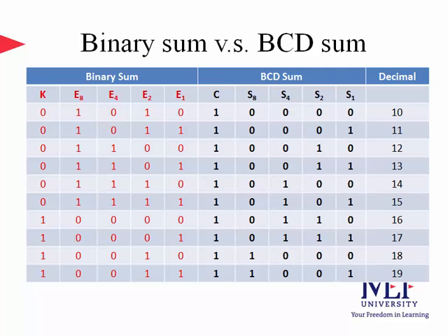As we have seen in one of our homework questions, adding the decimal number 6, binary 0110, to the binary sum will convert it to the correct BCD representation and produce the necessary output carry as required. So the next question is then, when do we need to add 6 to the sum for conversion? Apparently we don't need it all the time.